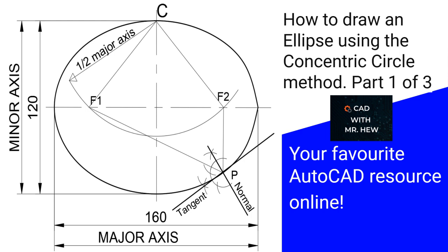The first thing you're going to do is to draw the center lines, the vertical center line and the horizontal center line. Then you'll draw two circles. The larger circle will be 160 millimeters for the major axis, and the smaller circle will be 120 millimeters for the minor axis. So we'll actually start the drawing now.